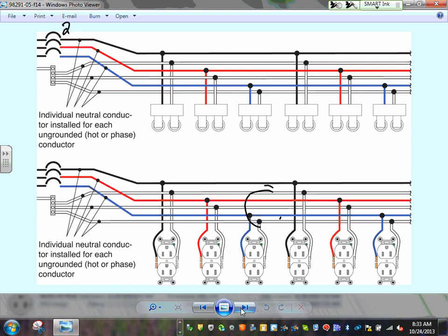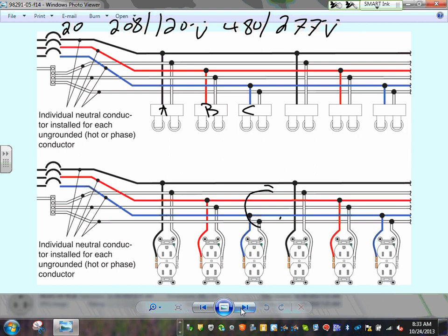So you have a 20 amp circuit here, and the voltage is 208/120 or 480/277 volt, right? And then you take a phase. Can you guys see how they're taking it? Let's start with this. This is phase A, phase B, phase C, phase A, phase B, phase C. Can I have thumbs up, Chad? We fully understand how to circuit with three phases. Adam, makes sense? Derek, Matt. So they take one phase and neutral, and circuit with three phases for your lights.